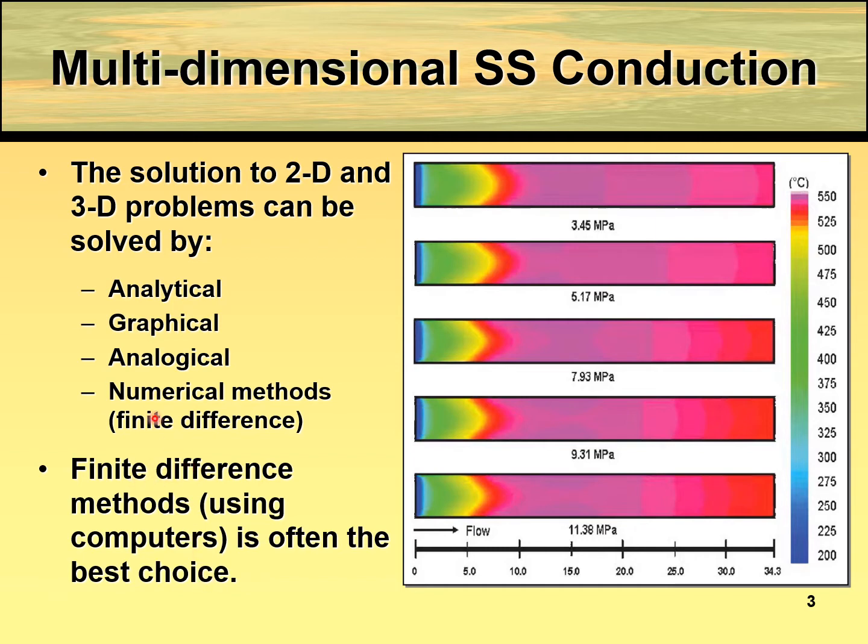So here we will see why we need computers. The reason is it involves a lot of nodes, and these nodes need to be solved by a computer program, and these nodes can be as many as a few 100,000 nodes. Right. So it's not possible to do this by hand, so you can only do it by computers. But in class we will learn how to solve the finite difference method by solving a problem which has only about 4 nodes, so that you understand the algorithm behind it, and then you can apply the same algorithm to solve problems using computers later on.